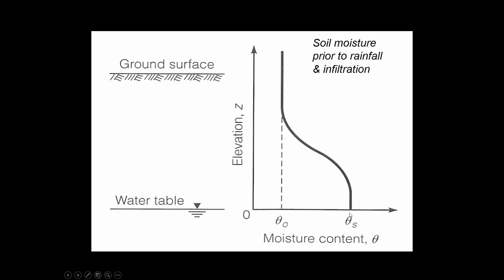What this figure shows is that even above the water table, there's an elevated amount of moisture because of the capillary effect, until we get to the typical water content for the rest of the zone of aeration. So there's this gradual decrease in the water content.